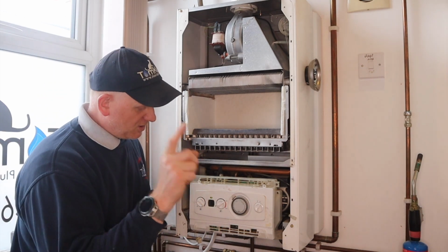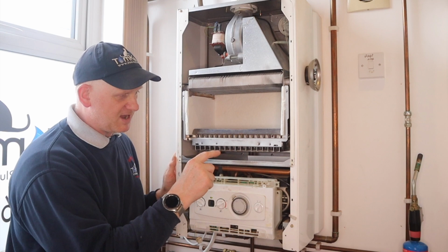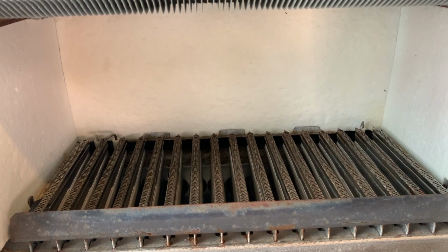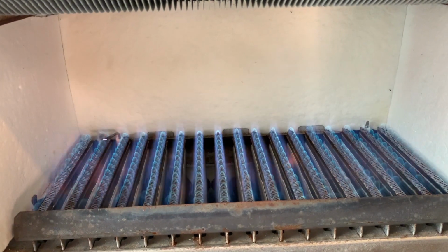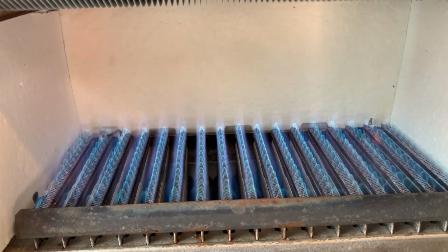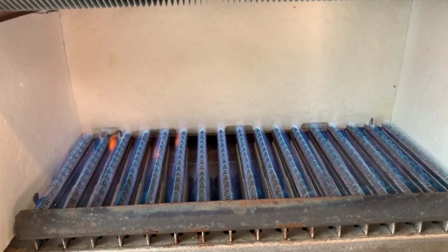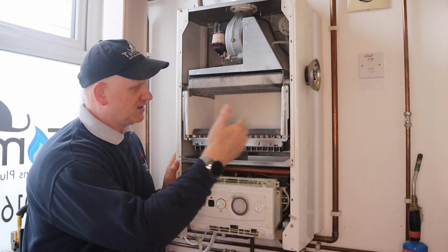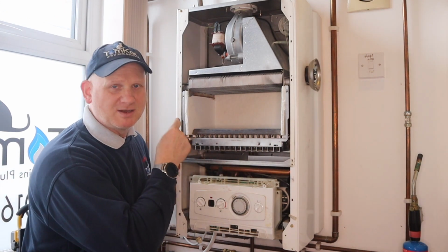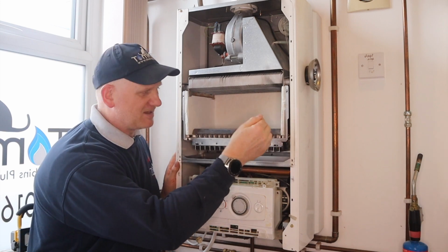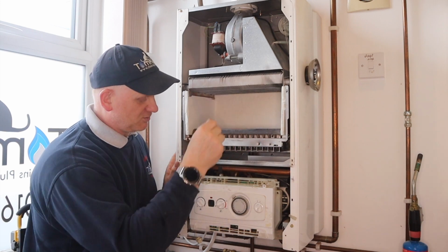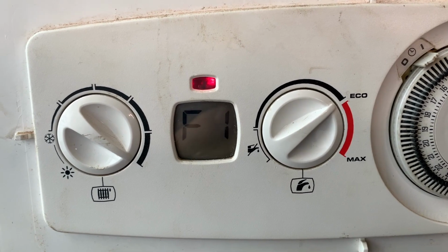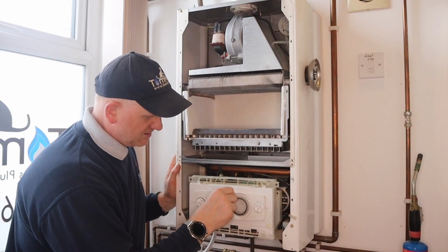So if I turn the time clock on now to call for heat, it should ignite and then go out. It's ignited. You can hear it still. So it didn't think it had lit right across because the ignition was still going, because flame rectification hadn't told it. So watch again, and it's put an F1 fault, which is the no gas. So it didn't know it had lit, it thought there was no gas. So if I reset it,